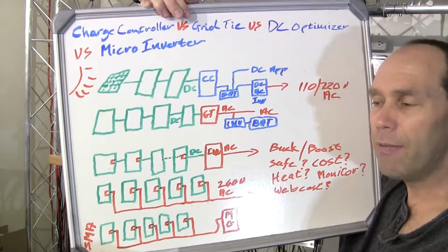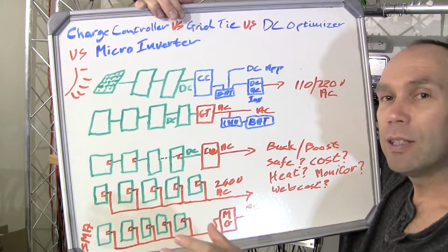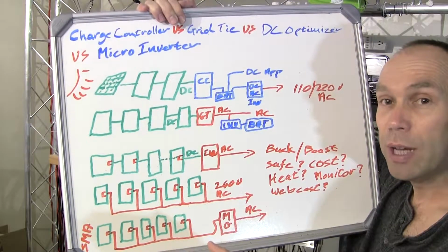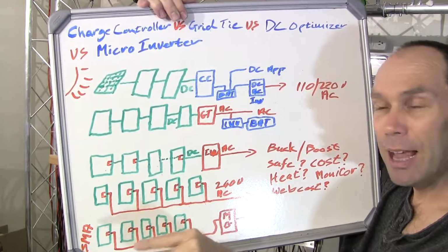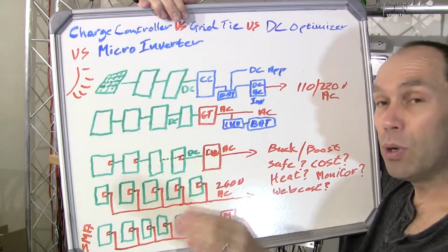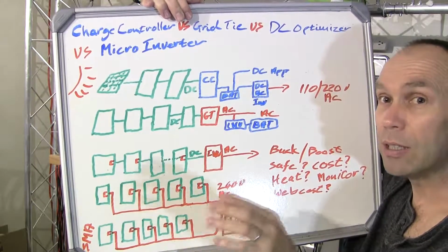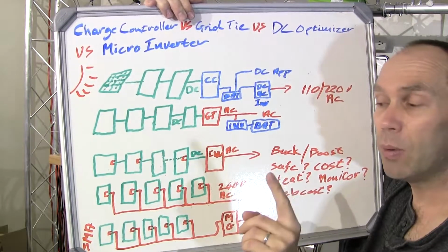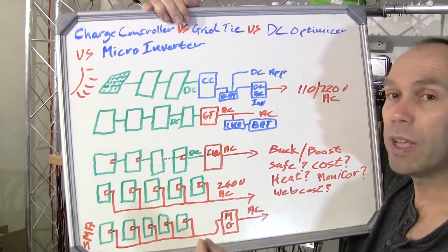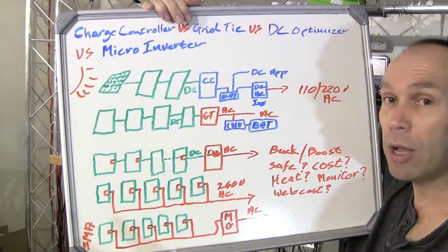And in the case of Enphase, at your initial installation of your solar panels, the system needs to be configured for the power system that you're running in your country. And you need that Envoy gateway to do that. After that is done, I think it purely acts as a data logging device, and the system will still work without it as far as I know, but it's something to be aware of and to double check. Once I get into further detail of the individual products, that is something I'll highlight because that could potentially be a gotcha.